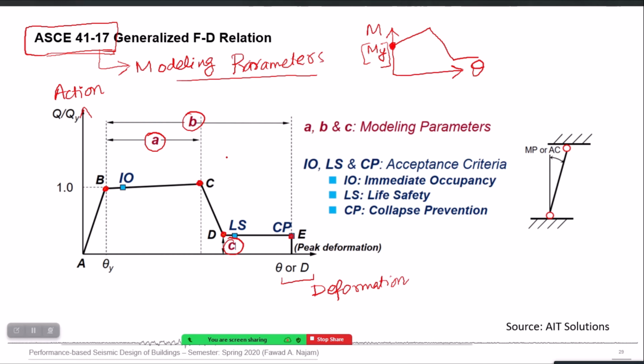So once the bending moment crosses the capacity, then the hinge will be activated during the analysis, and it will tell the program that now the bending moment should not increase indefinitely with the applied loading. It should increase up to a certain level, maybe with this slope, and then beyond that it should just come down and the beam should be considered failed. So this is called a rigid plastic hinge. Rigid plastic hinge means that the linear part of the behavior there is no need to define, and it can just behave in a rigid manner.